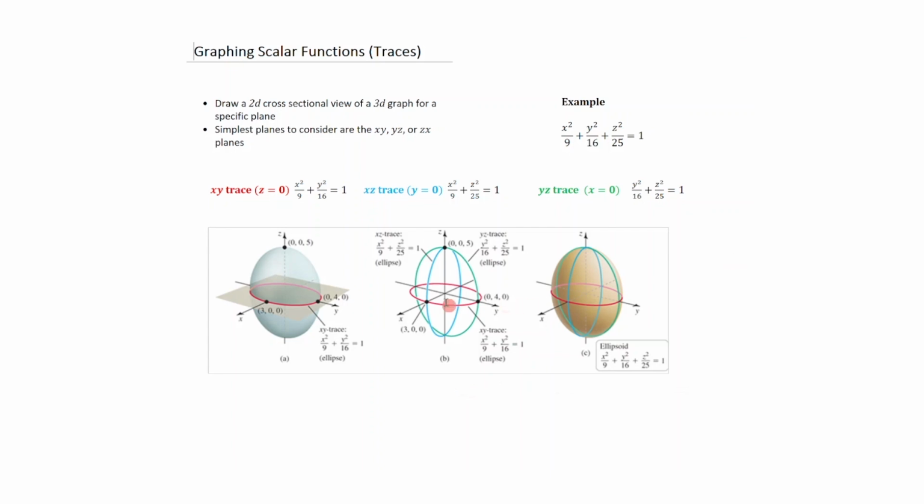All right, so if we move now to B, we can look at the other 2 cases. So we have the red one. Here's the case from the xy trace. And now basically do it for the xz trace and yz trace, and you end up with similar lines, but one of them is on the zx plane and the other one is on the zy plane. So if you take those 3 sketches, looking at them, they form a scaffold. And so from that, you can piece together what the exterior surface would look like. So it's a technique that helps you understand how to sketch it.